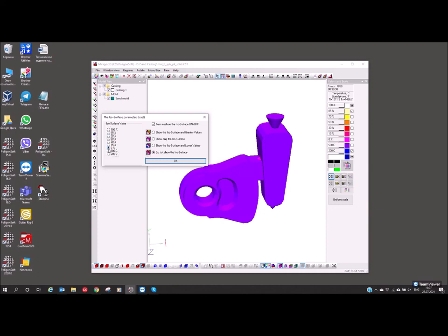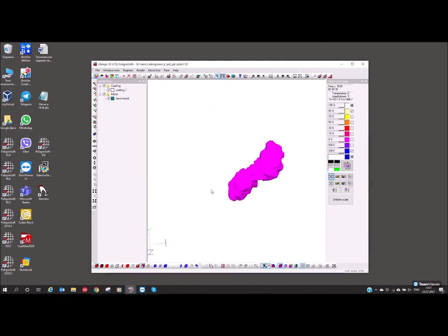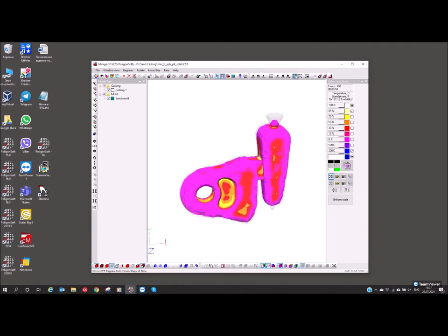For example, if we set the 0 liquid isosurface and show the isosurface and temperatures higher than this isosurface, like this, and I will switch on transparent cast. So we will see only the parts of the casting with liquid metal inside. For example, it looks like this.